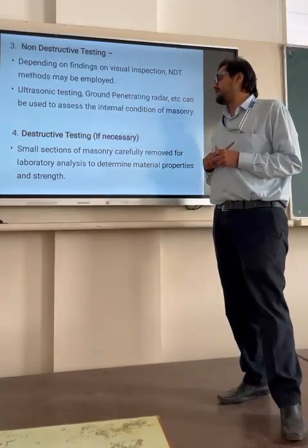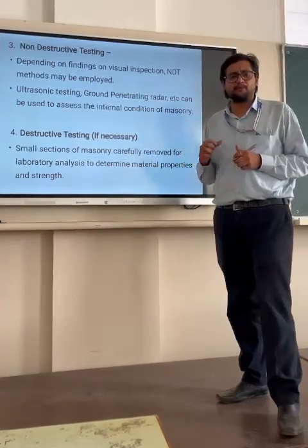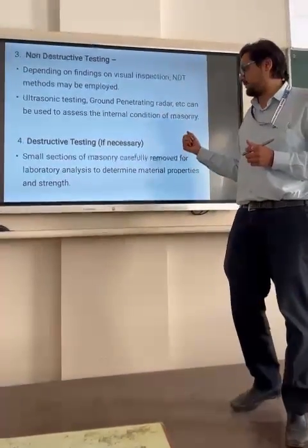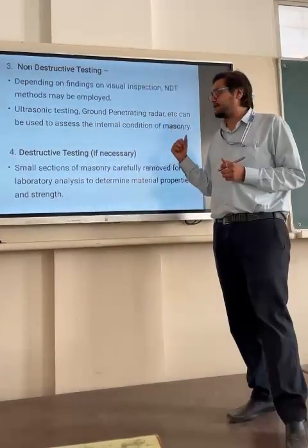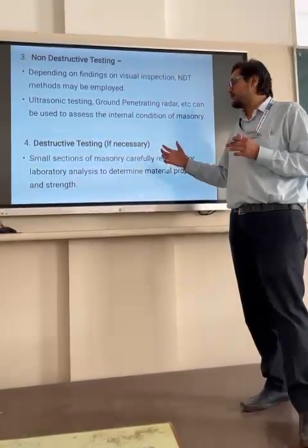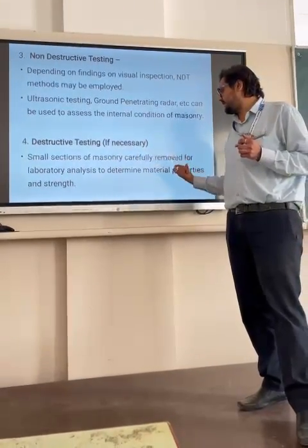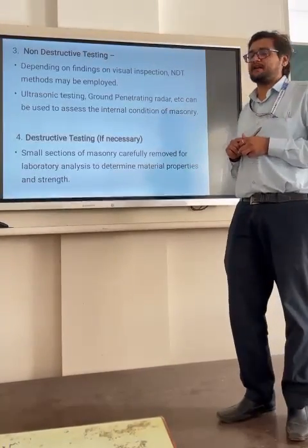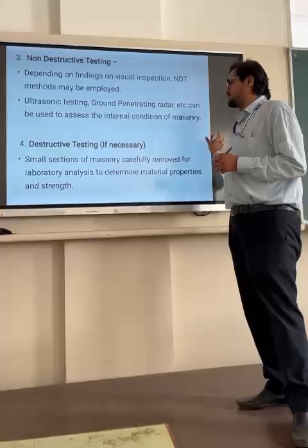Then there is destructive testing, and this step is generally used only if it is necessary for that structural audit. Small sections of the masonry are carefully removed for laboratory analysis to determine the material properties and strength of the material. So this is the fourth step.